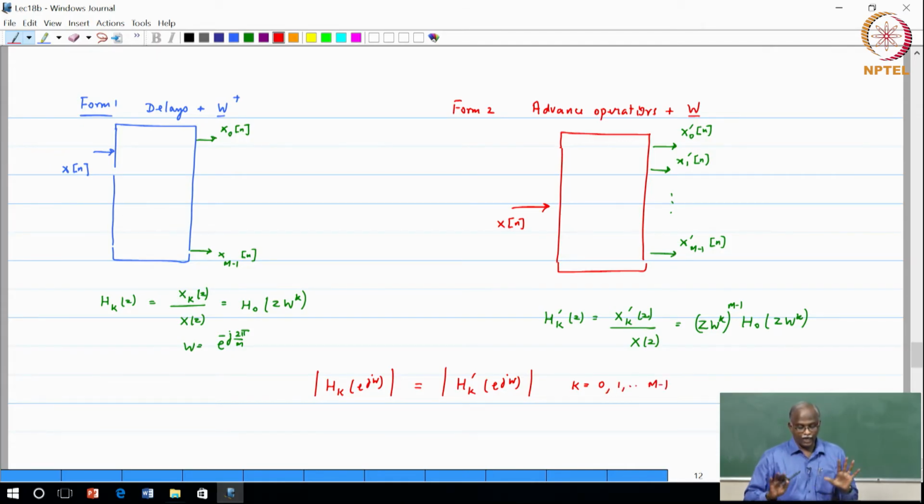So, these are equivalent forms, both of which are useful for spectral analysis. Both of them use the rectangular window as the underlying filter. It is not just a delta function sampling your signal spectrum; it is your signal passing through a filter which has a well defined frequency response. So, this is useful for us to keep.